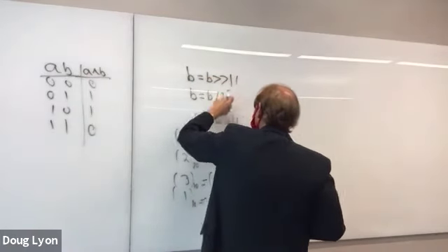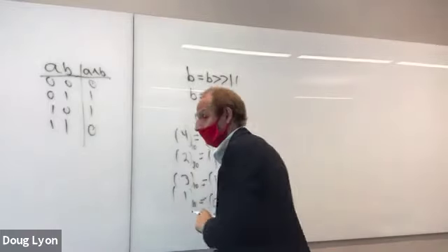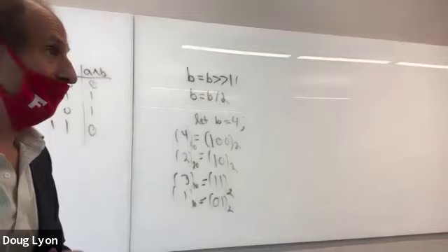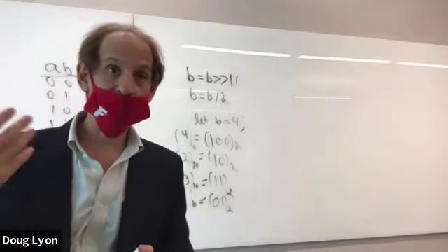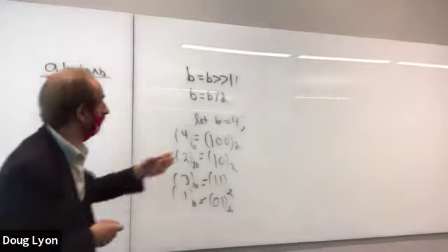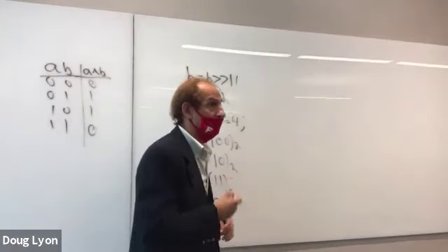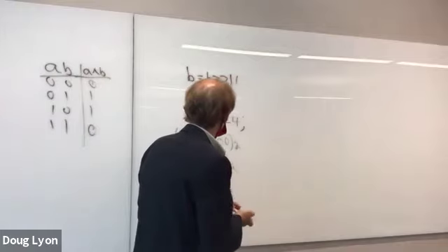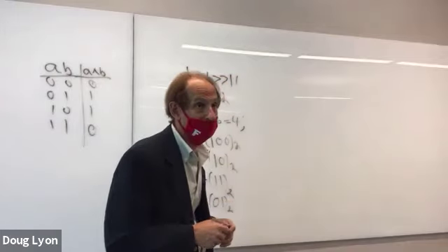But if you wanted to do that, then you would have to divide through by 2 to the 11. And division, generally speaking, takes more CPU cycles than shifting. A barrel shifter will be able to do the shift operation in one CPU cycle, whereas a division like this could take several cycles.